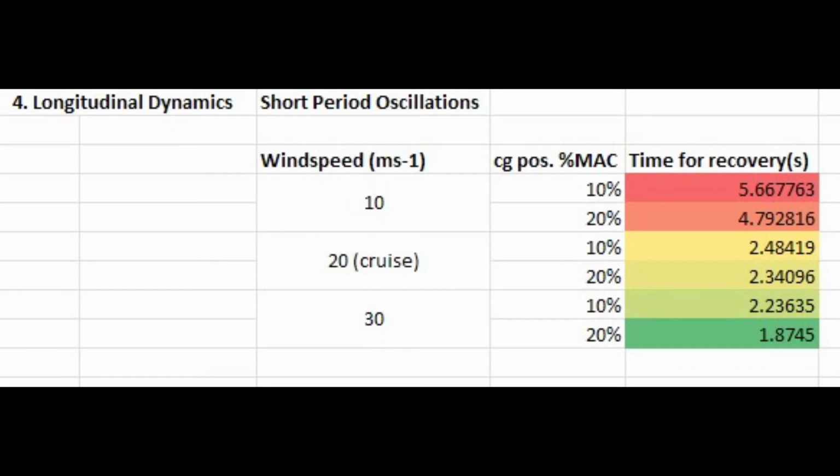Varying airspeed causes differences in control response, where higher airspeeds delivered greater control than lower airspeeds, where much less damped control is exhibited. Also seen is that moving CG position forwards benefits the aircraft, reducing the time taken for pitch response. It is worth noting that testing at CG position of 30% MAC resulted in severe instability of the aircraft.